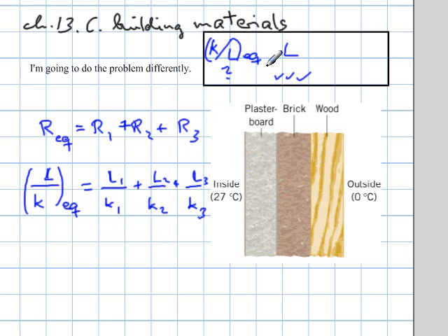So as I said, the given K's are 0.3, 0.6, 0.1, and when we put them together, the overall result should be less than any one of them, so it should be less than 0.1. Okay, let me plug that into the calculator. As I said, I'm going to keep the L as 1 unit, so I'm going to have 1 divided by the first K, which is the 0.3, plus 1 divided by the 0.6, plus 1 divided by 0.1.